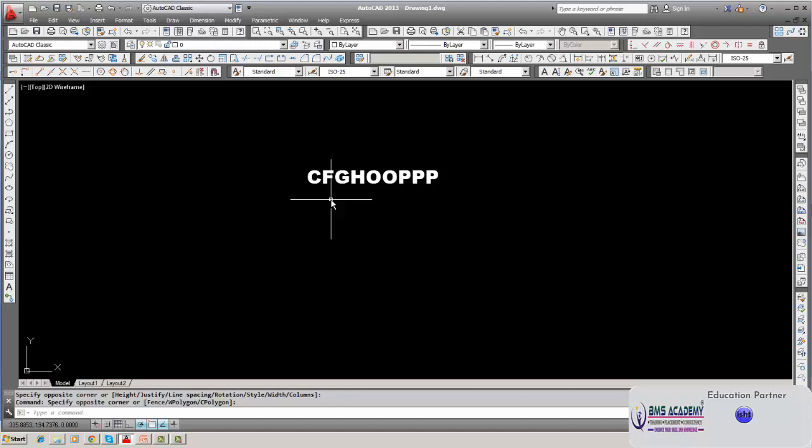Such a drawing we have made in the AutoCAD. In the AutoCAD, this is called model space. This screen is called model space. In this space, you will always draw the part to the full size. Suppose 1 meter into 2 meter means you will draw 1000 millimeter vertical, 2000 millimeter horizontal. It will take such a big size also. There is no problem. Only when you want to print it, then you have to reduce the size and give the printing command. While reading on the drawing, you can read it. While printing, you have to reduce the size.